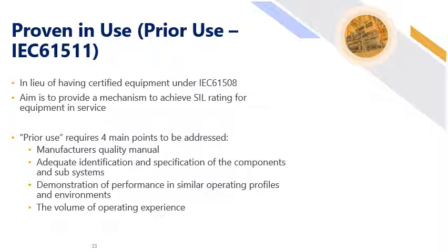And then for your own experience, you need to prove a certain volume of operating experience. And all of this can be developed over time. So it is possible to develop a SIL function without certified equipment, but there's much more onus on the operator to make sure that the data they're using is accurate.